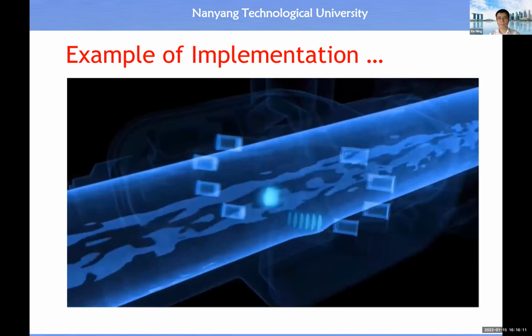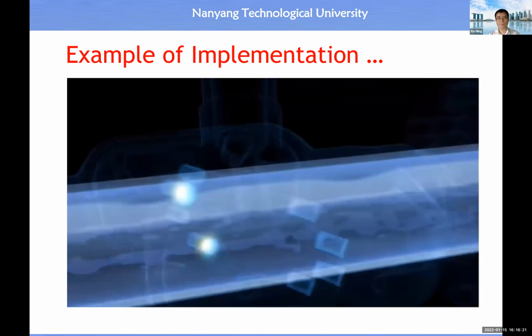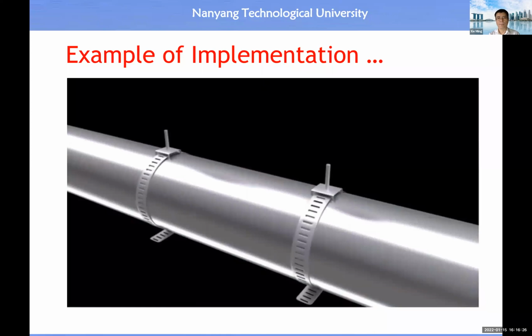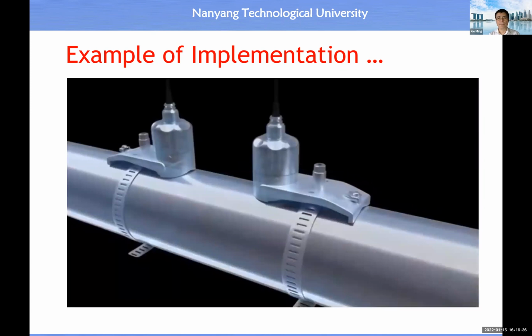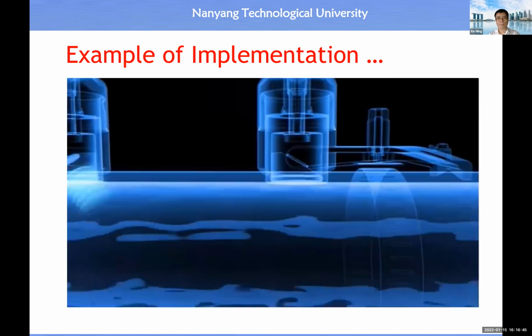For ultrasonic flow measurement, the sensors do not necessarily have to be fitted into the pipe wall. With a clamp-on system, for example, the sensors are fastened directly onto the outside of the pipe. They can be retrofitted at any time without interrupting the process. With clamp-on sensors, the ultrasonic signal is passed directly through the pipe wall and into the fluid. The signal continues through the fluid, is reflected on the opposite pipe wall, and then measured by the second sensor.